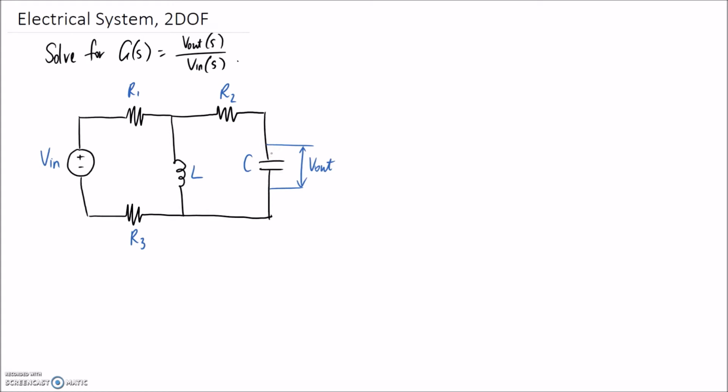So in terms of the approach to this question, for the electrical ones, you can either use the mesh analysis or the nodal analysis. But I tend to prefer the mesh analysis, and it's especially good when you have voltage inputs to your system. If you have current inputs, then nodal becomes sometimes more appropriate. So I'm going to apply mesh analysis, and what we need to do to set this up is draw in the current in each part of our mesh. So this here is going to represent one mesh, and I'll call the current running through it I1, and this in here is going to represent a second mesh, which I will call the current I2.